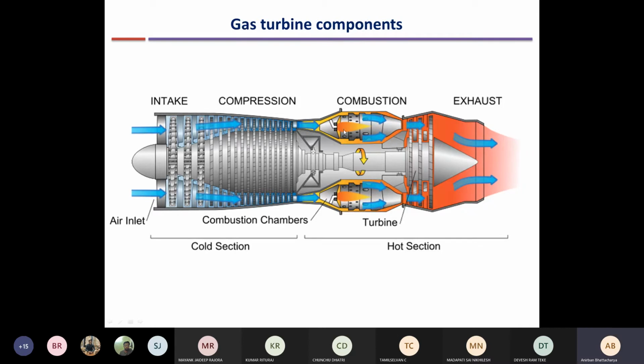So what is done is, locally there is some low velocity region where the combustion can be sustained, and then an additional amount of air is introduced downstream for the mixing to occur. In a local region, there is a small amount of air, known as primary air, which is introduced at a very low velocity for the combustion to be sustained.